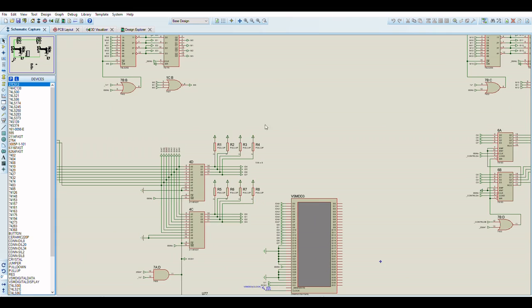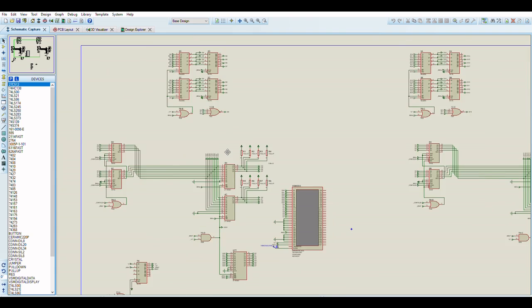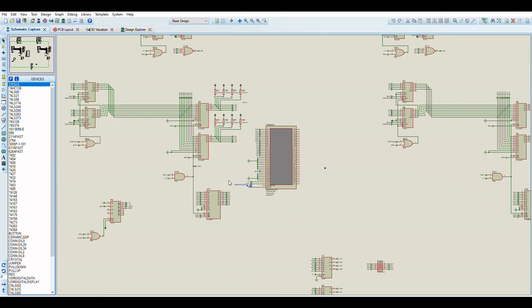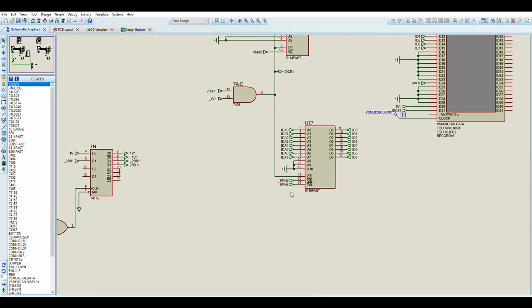Because as you can see, up here, the 6 MHz clock is used to strobe the write enable, and the 6 MHz and the inverted 6 MHz clocks are used to strobe the output enable or write enable, respectively. So with these scanline RAMs filled with FF, what happens is this.